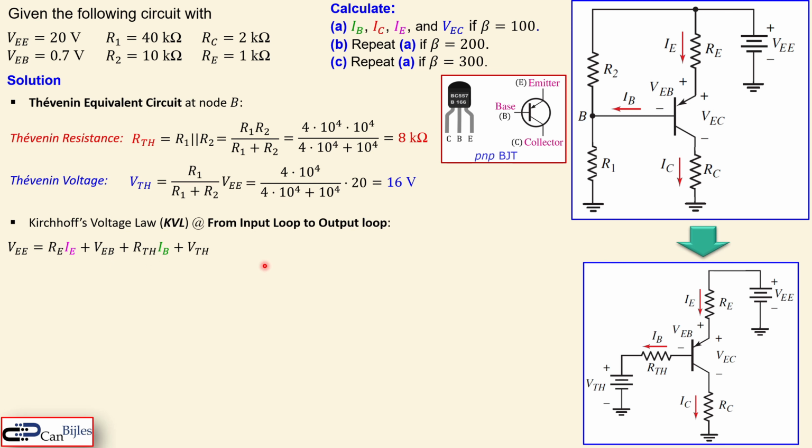But we need to set up the equation, and we start with the base current. It's always handy for these kinds of circuits. So I need to replace the emitter current here in terms of the base current. We know that in linear region operation, for the NPN or PNP transistor, it doesn't matter, we have this expression, beta plus 1 times IB. Now if I substitute this expression in this expression and collect them together, I have an expression with only IB as an unknown, because I have the rest of the parameters.